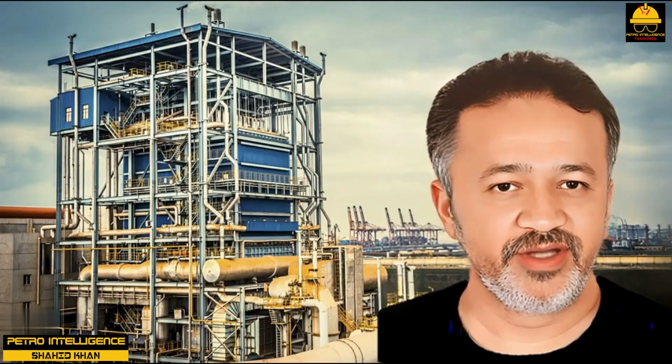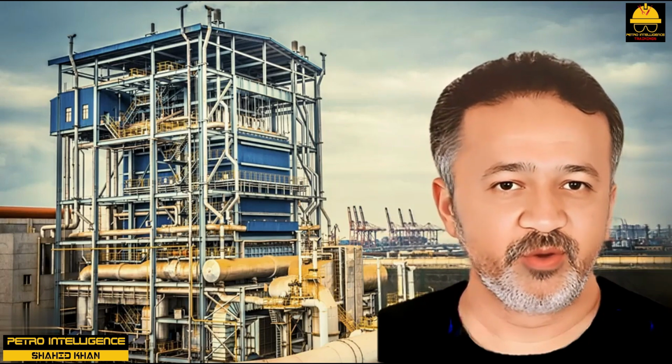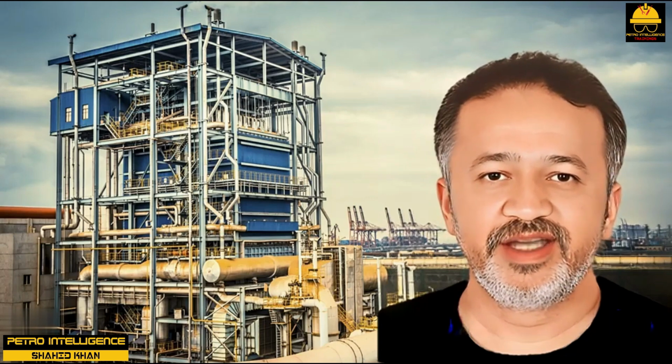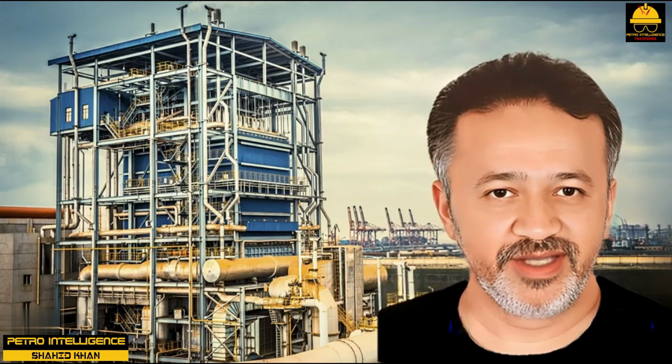Spiral heat exchanger. The spiral heat exchanger concept represents a completely different type of construction as compared to heat exchangers or coolers with tubes or tube bundles. In this quite different design, there is only one channel per medium, thus the design aims to eliminate the possibility of channeling and suppress fouling.